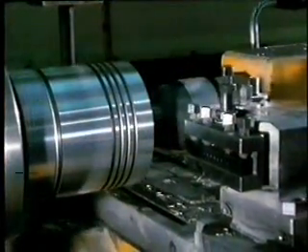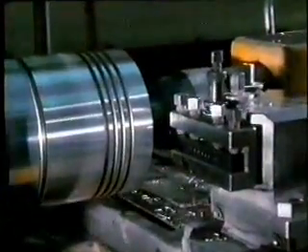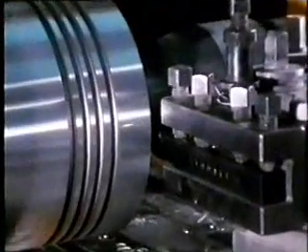These tools can be used for a variety of cutting processes with non-ferrous metal, and they are particularly efficient for cutting aluminium alloys and castings such as pistons. These alloys, which contain highly abrasive silicon particles, a test for any material, are easily machined. A synthetic diamond tool, although initially expensive, can last up to 10 times as long as the tungsten carbide equivalent, and when used for intermittent cutting.